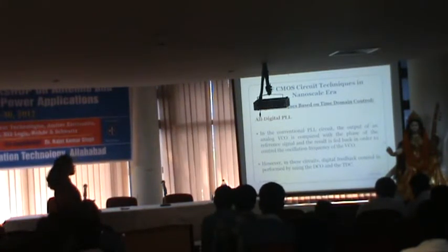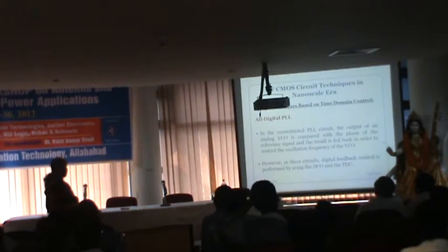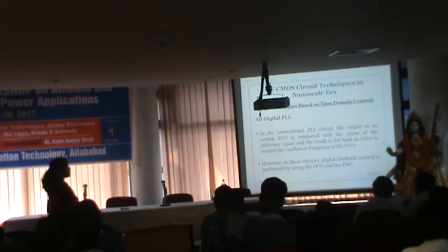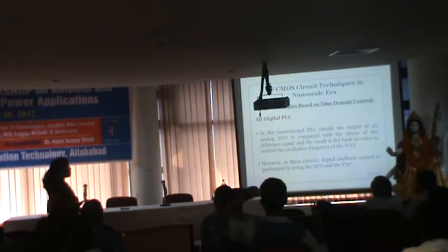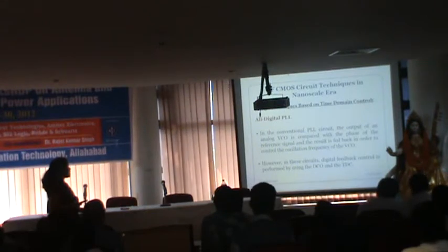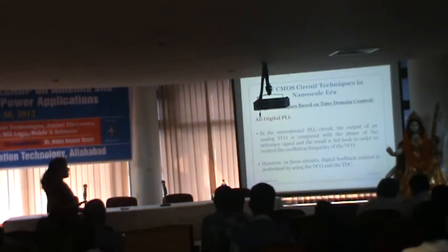Now here I will be talking about the RF CMOS circuit techniques in the nanoscale era, where we are actually already designing. There are different techniques. One is the design techniques based on time domain control. In this category, we already talked about all-digital PLL.